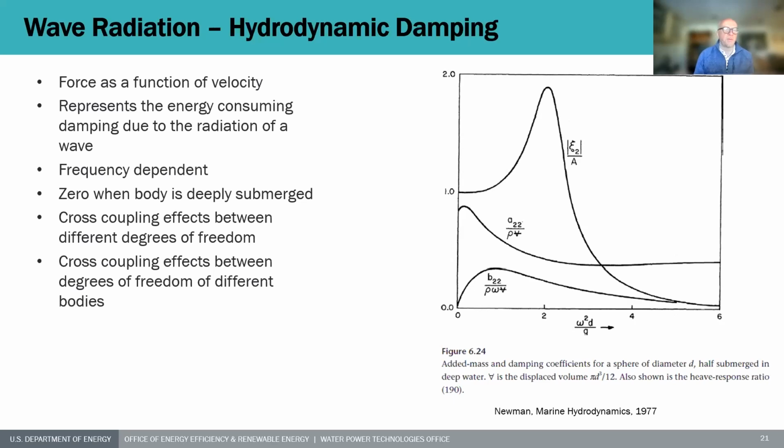I can lose it if I radiate waves. And this behavior is, like waves, frequency dependent, so also the hydrodynamic damping, the radiation damping, is frequency dependent. And it only occurs when I'm close to the surface, when I actually can radiate waves. It's zero when we're deep down in the water. Okay, and the same cross-coupling over the different degrees of freedom as well as different bodies occurs.